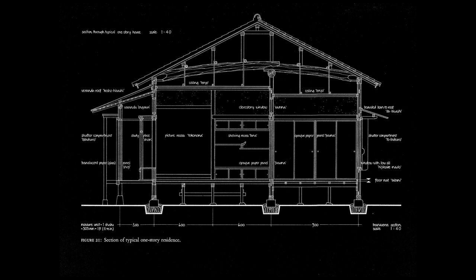And this would be more or less enough for a carpenter to know what he had to build. So actually no design, let alone an architect, was necessary. Even the height of the ceilings, I always like this idea, the height in the system, was related to the size of the room. So an 8-mat room gets a higher ceiling than a 4-mat room, for example. So even this, the carpenter even knew how high he had to make the ceiling of each of the spaces.